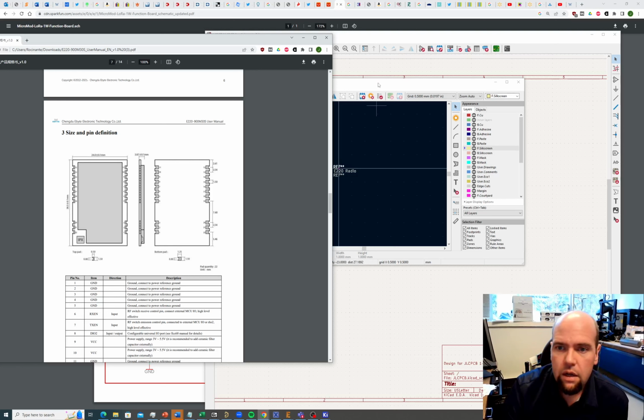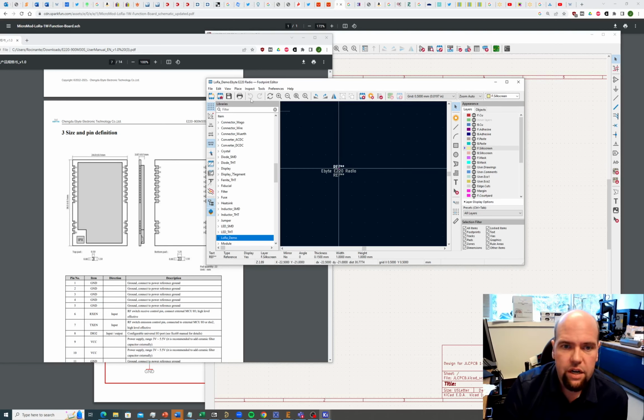So to start, before I get to the pad, let me just do the outline. I like to start with the outline for the part. A lot of people draw it later. A lot of people start with the pads. If I start with the outline for the part and I know it's correct, it's really nice because it lets me have a sanity check as I'm doing this, that things are in the right place. It'll make it look like what I'm expecting. It's not the only way to check it, but it's a way to sanity check. So this thing's 24 by 38.5 millimeters.